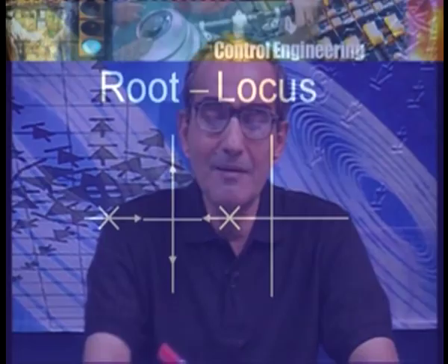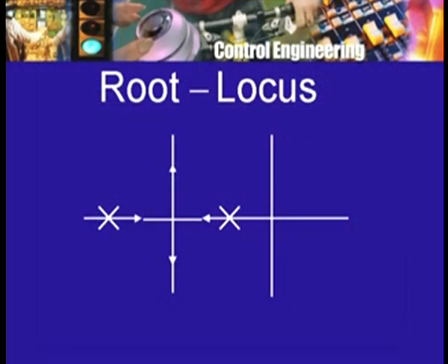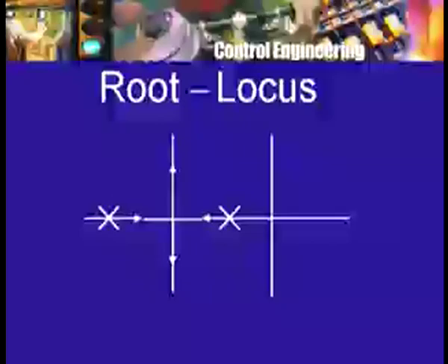drawing the root locus. But on the other hand, if one studies the root locus method sufficiently, then there are some conclusions which one can draw from the root locus method almost immediately. Of course, with some practice, the same conclusions can be drawn using the Nyquist approach. For example, we had, let us say, to start with only two poles, no zero. So, what was going to be the nature of the root locus? Well, these two coming together, breaking away and going into the complex plane, no instability, but maybe oscillations beyond a certain value of the gain k.